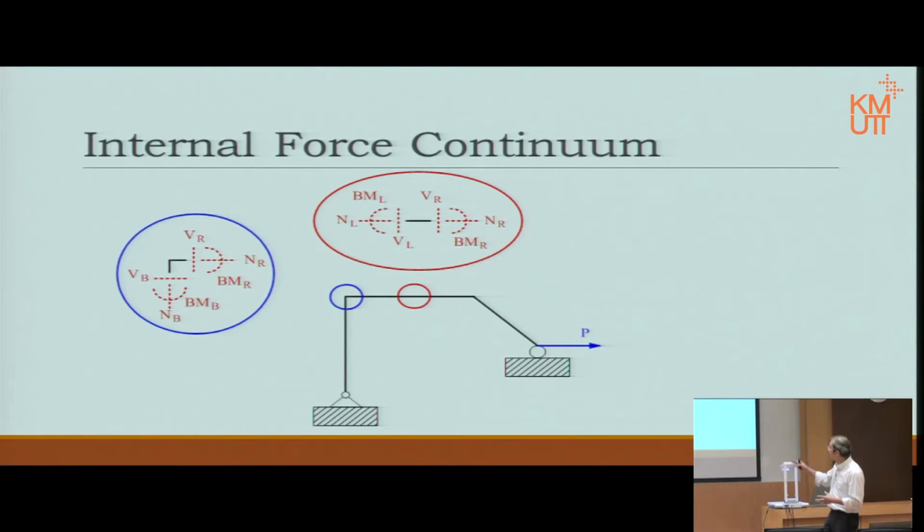However, if we look at the joint where the two members meet, the two members that have different directions, in this case we're talking about a column and a beam. The vertical line represents a column, the horizontal line represents a beam. On that connection, if we look at that point, again I'm talking about a point. Remember the definition: the definition of shear is not vertical or horizontal. The definition of shear and axial force is in relation to the line of the member. Namely, the axial force will be parallel to the member, and the shear force will be 90 degrees to the member.